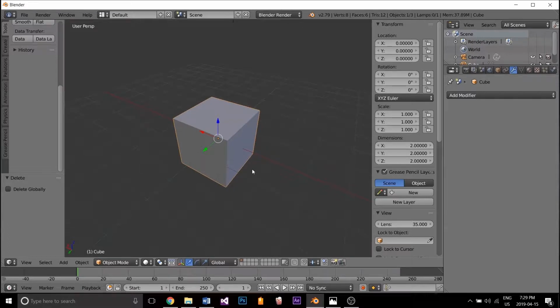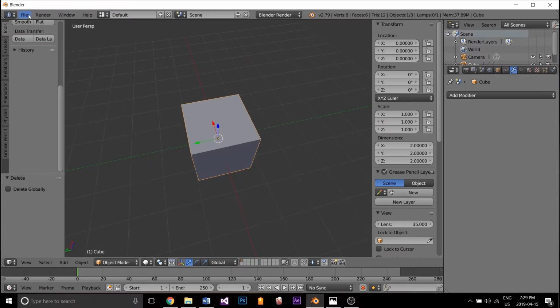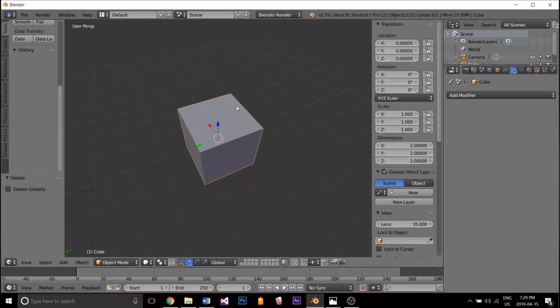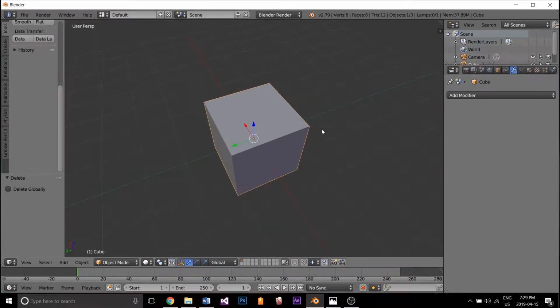The origin point is necessary for most of your modeling. This is where you have your grid, you have your different blend units, which equal out to different actual measurements in real life. Blender's default, I believe, is set in centimeters. You can change that in the user preferences using File, User Preferences. You can change it to be meters, kilometers, imperial, and metric systems alike. So let's go into our model, and I don't like the toolbars being in the way now, so I'm going to click N. I do, however, like the toolbar T for different knife tools, skew tools, and all of those to be open.